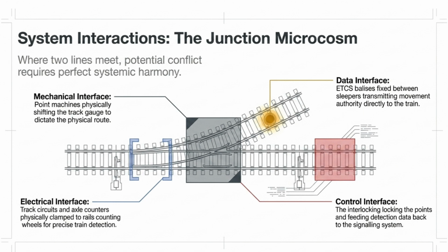If they don't account for that vehicle overhang, the signaling system might actually think a junction is clear, when in reality, the nose of a train is still sticking out and fouling the adjacent line. It's just a perfect example of two totally different subsystems requiring exact dynamic coordination.